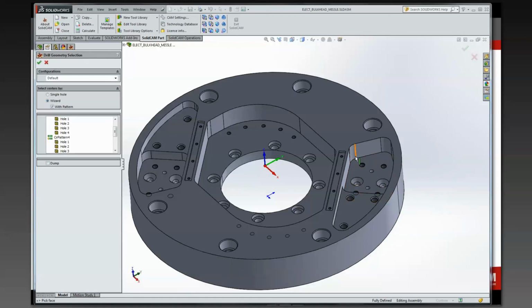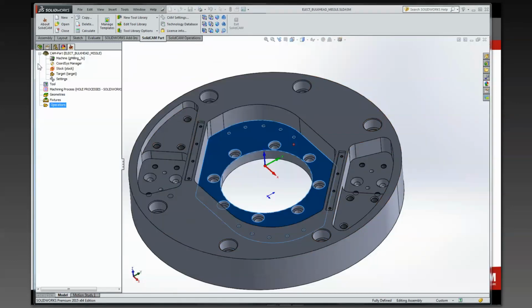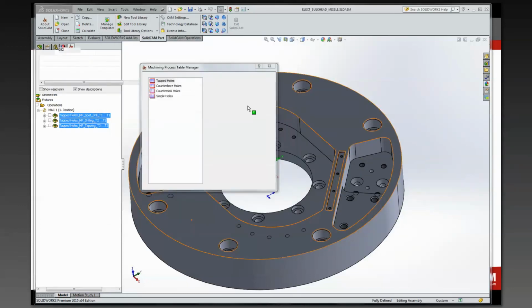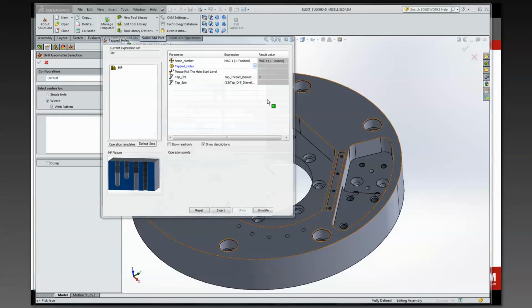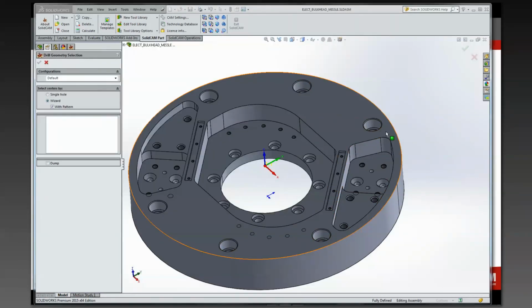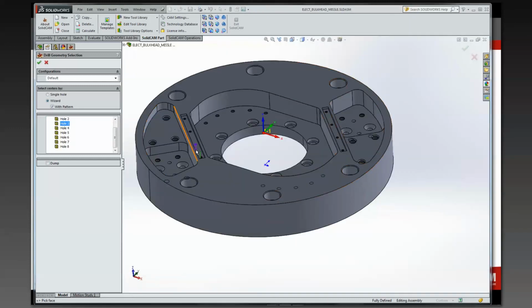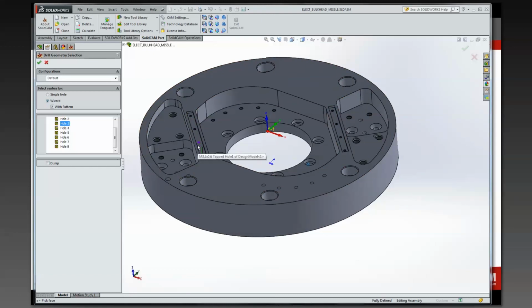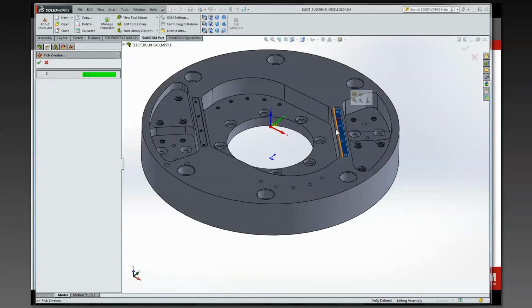Okay? That Z value pick is down on this elevation. So I'll insert that, reset this. Now I'm going to go back in. I'm going to recognize this little bitty hole here. Okay. Notice again, it found all of them, including the patterns over here. So it knows that this whole set was patterned over to this on a circular array. Again, a different Z level here, so I need to pick the start point there.